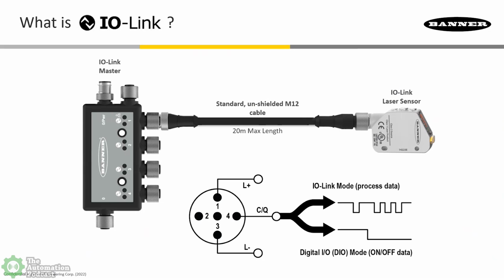To me, it's exciting because I kept seeing sensors getting all these advanced features, and I had to go down to the sensor, plug in, and hit all the buttons to set things up, and there was no way to get that detail back into the controller. But IO-Link unlocks that. It says, hey, this intelligent sensor you have, now that data can come back. In many cases, you can even configure one of these sensors via software over IO-Link. That's what got me excited when I first saw it.